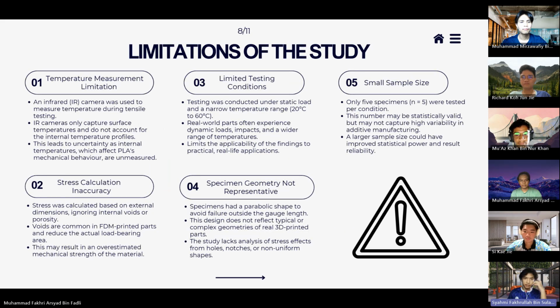Alright, I'm Shahmi and I'll present the limitations of the study. The first limitation is temperature measurement. This study used an infrared or IR camera to measure temperature during tensile testing. However, IR cameras only capture surface temperature and do not account for the internal temperature profile of the specimen. This leads to uncertainty, as internal temperature affects PLA's mechanical behavior.